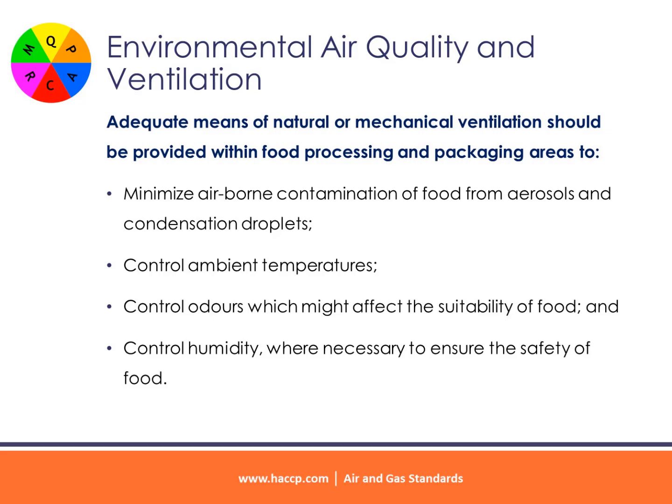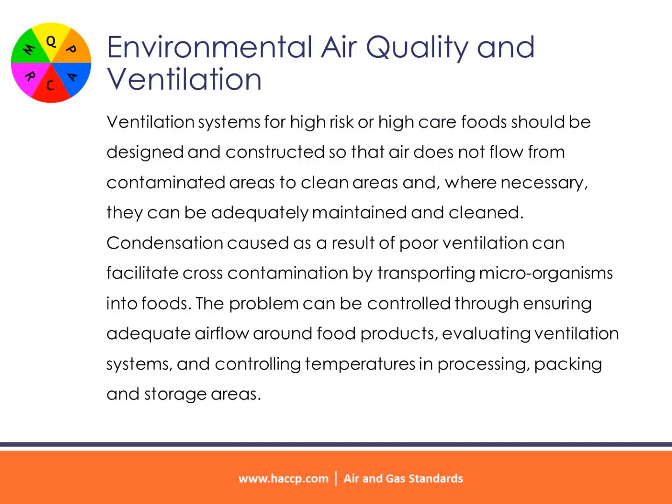Control ambient temperatures. Control odors which might affect the suitability of food. And control humidity, where necessary to ensure the safety of food. Ventilation systems for high-risk or high-care foods should be designed and constructed so that air does not flow from contaminated areas to clean areas and, where necessary, they can be adequately maintained and cleaned.